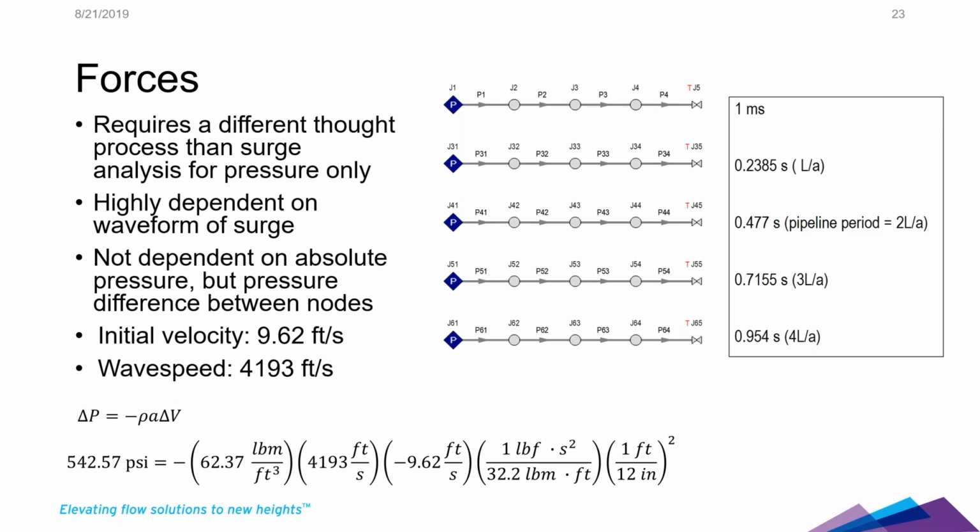So we're looking not at a force at an area, unless you're maybe discharging to atmosphere, that's a different case. But if you're looking in between pipe nodes, pipe force sets, it's all about pressure difference between nodes. You have a force over an area, and a pressure over an area is a force compared to the other pressure over an area. That's dP, not absolute P. Okay, it's your differential pressure that matters. In this system, they're all the same.